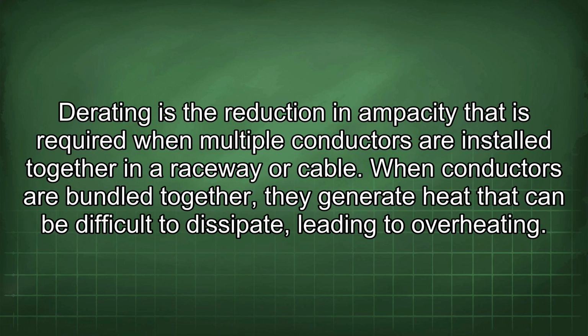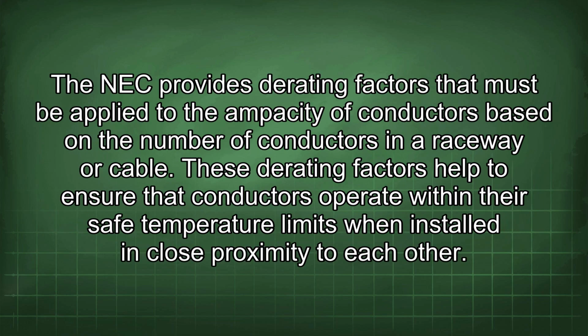Derating is the reduction in ampacity that is required when multiple conductors are installed together in a raceway or cable. When conductors are bundled together, they generate heat that can be difficult to dissipate, leading to overheating. The NEC provides derating factors that must be applied to the ampacity of conductors based on the number of conductors in a raceway or cable. These derating factors help to ensure that conductors operate within their safe temperature limits when installed in close proximity to each other.